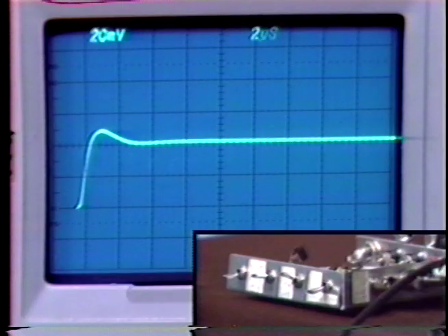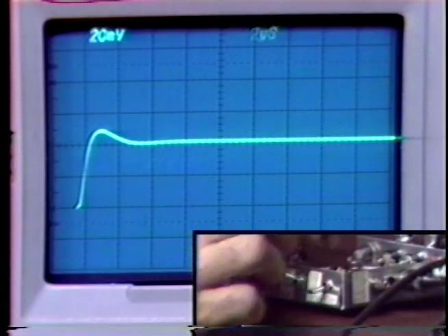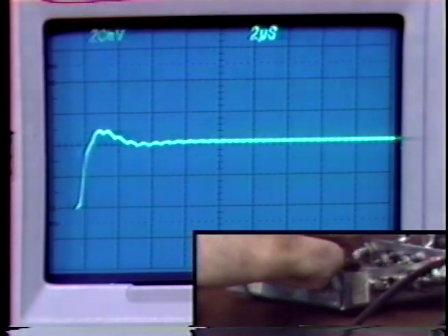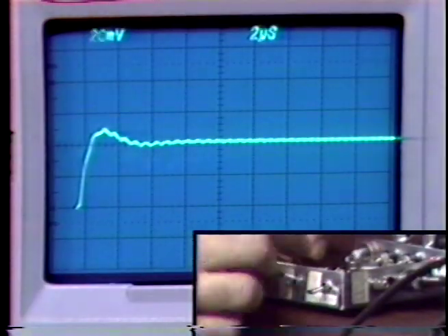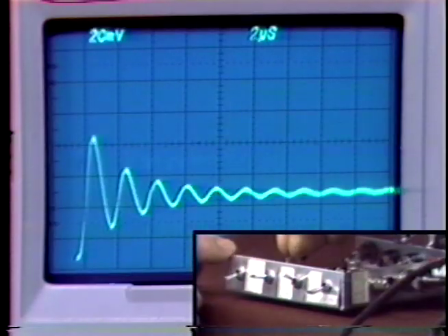We've eliminated the minor loop problem by making the compensating network look capacitive at the crossover frequency of the minor loop. That frequency, of course, is much higher than the overall crossover frequency. Let's do it once more. Let's take out that capacitor. The teeth come. We add the capacitor back in. Simply move this lead over.